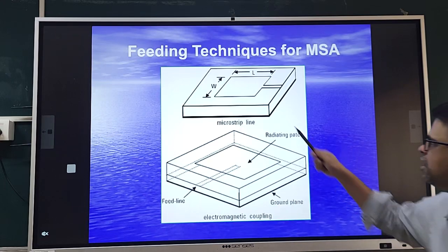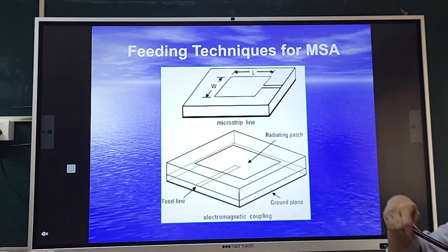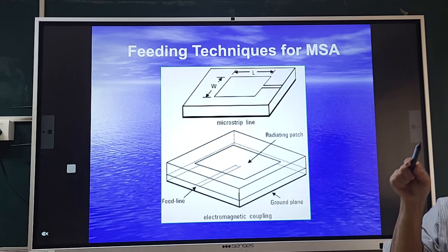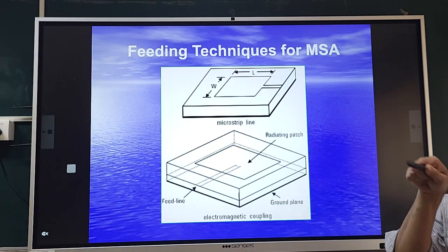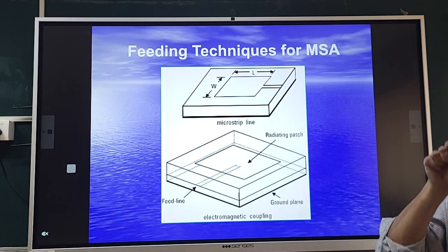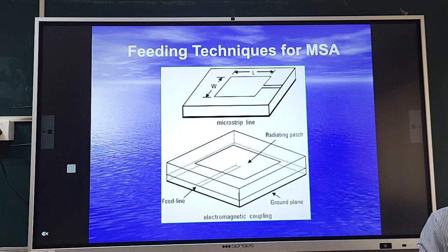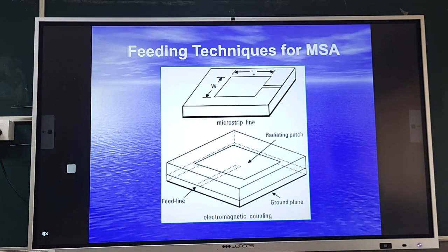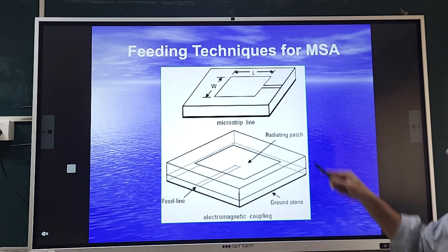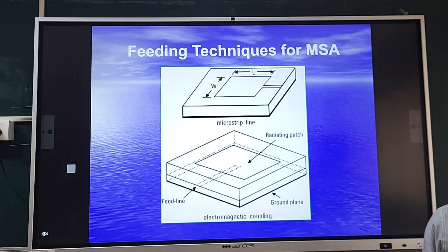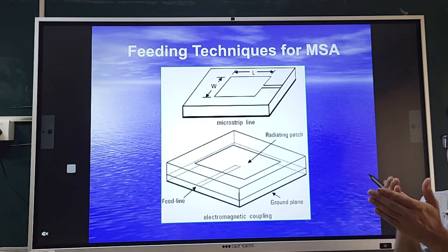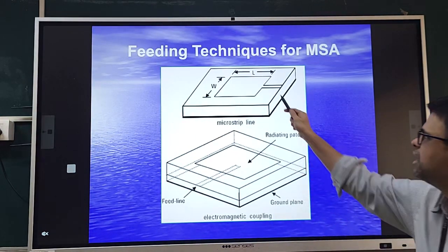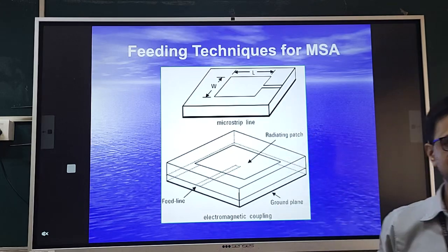Okay, so here, similar to the coaxial feeding technique where you need to fix up where your 50 ohm point, 60 ohm point is on the patch and then drill a hole, similarly here you need to first calculate what the edge impedance is, and then decide the impedance of this line. Because, as the principle of impedance matching goes, the impedance at these two junctions should be matched.